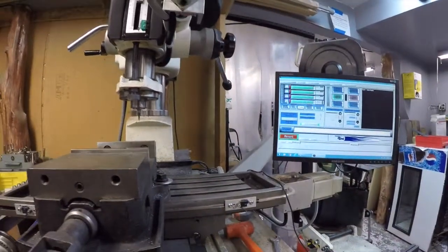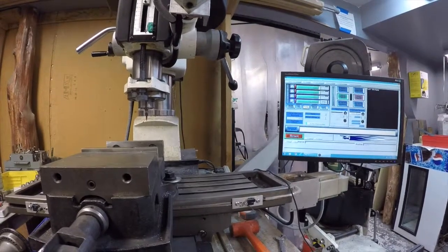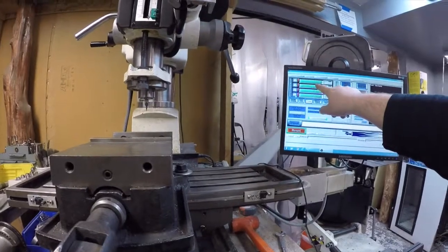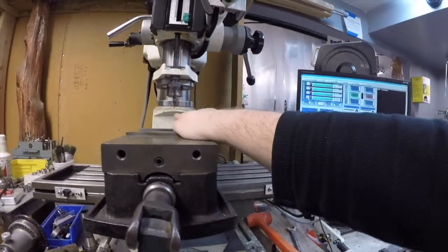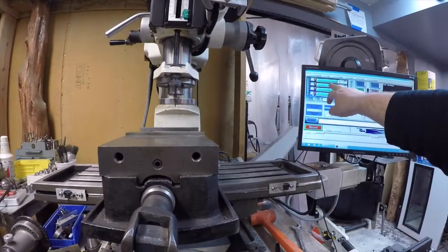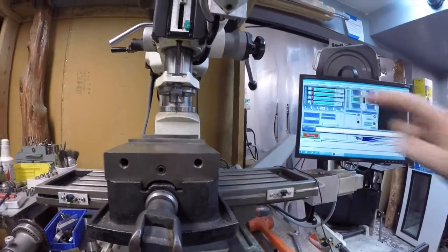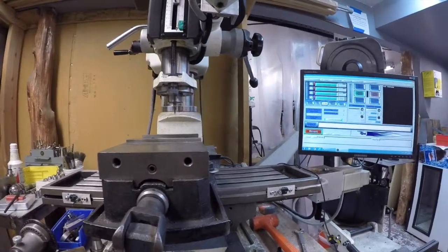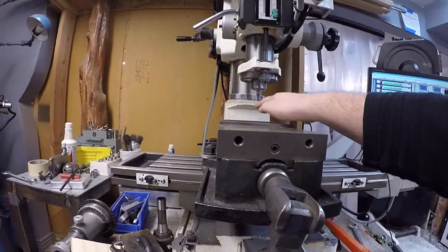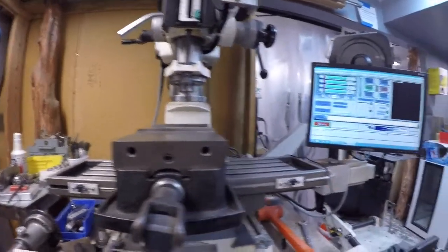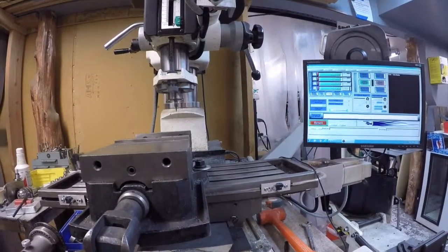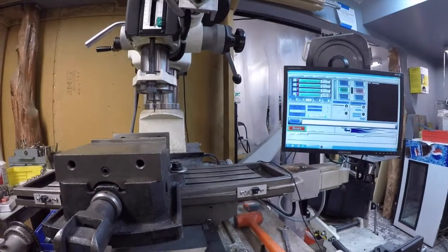This is really important. If I go to the right, see how this X goes negative 1.1022? That means that the effective position of the end mill is now negative 1.1022 inches away from where it started. So if I move this back to the right, again the table's going to move to the left, but you can imagine that this is effectively moving to the right of the cutting surface. If I move it back to the right, I can move back to about 0.